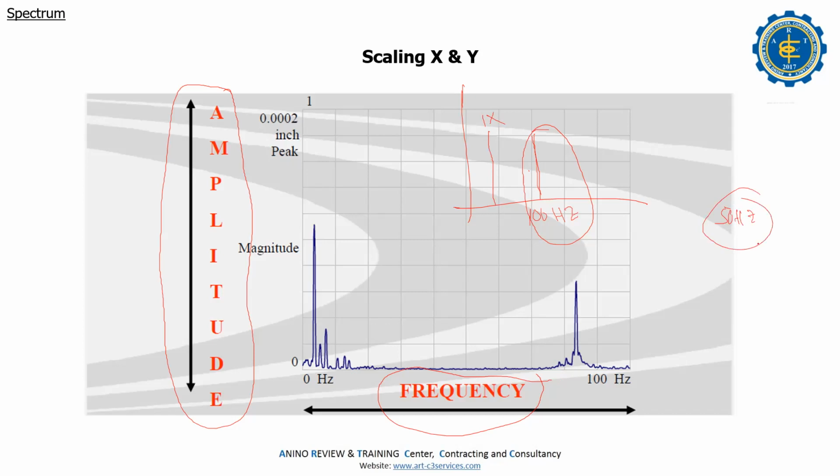it is easy to identify that there is a misalignment or that there is a problem with the electrical. Because if there is a misalignment, we have 2x. This is 60, then 120, right? Then it is misalignment. 180. So then you have an electrical problem with 100 hertz. Then it is easy to identify that there is a misalignment or electrical issues.